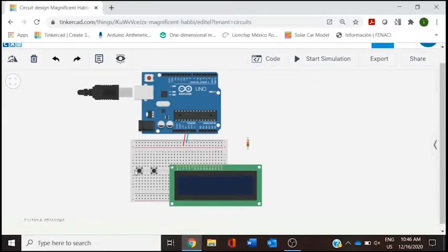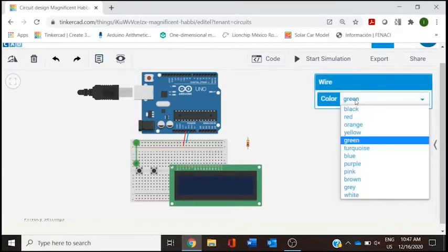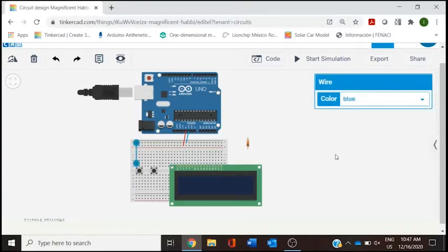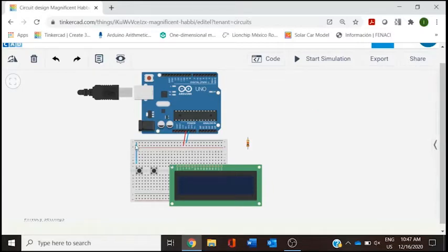So we are going to start with the first push button. It has 2 connections here. The left one usually goes to ground, so we are going to connect this one to ground, changing to blue, so we will identify that we are working with the negative side. The next pin goes to the Arduino Uno. In this case, this connection is going to digital number 2.